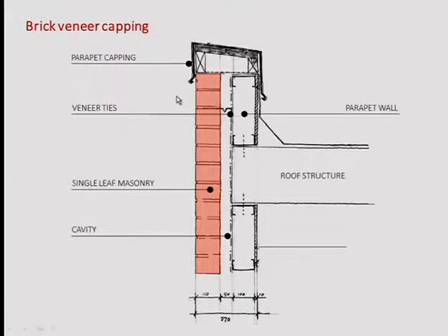Capping on the top, a little bit less interesting, but again, there is a point in which we can actually assess the cavity of the brick veneer here. What we do, we just place a capping, we bring water towards the interior sides and we collect it here. What's interesting to note in this detail is that this is not a timber structure, so this type of brick veneer section works well also if you have steel profiles. So you see that these are steel profiles, but it's actually the same size, the same type of detail, exactly the same.